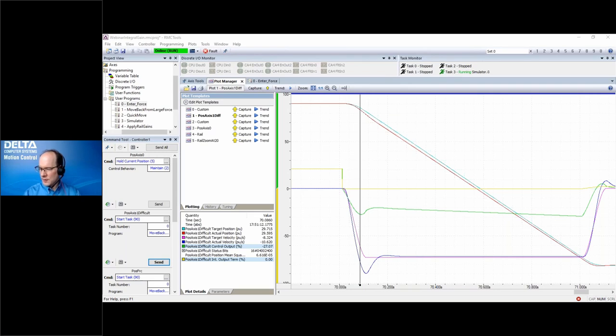Is that fairly normal? Okay, if your system has a big offset, like if you have a traditional servo valve, jet pipe or flapper nozzle, those can tend to get out of null, and sometimes they can be very much out of null. I went on a system and given open loop voltage of 0, and the thing just shot off because the null was off by 40%.